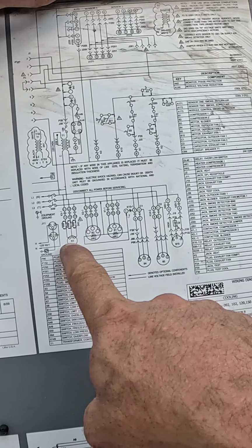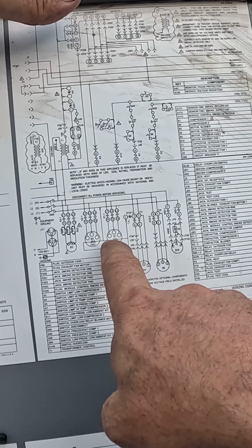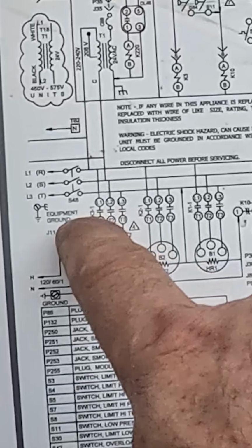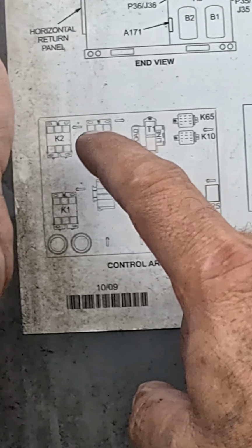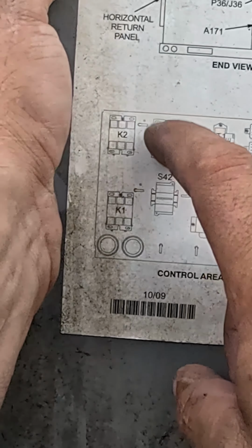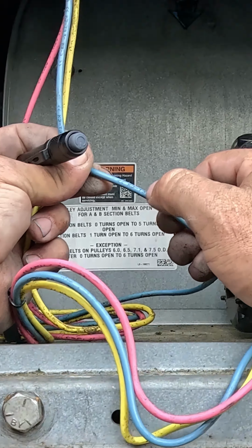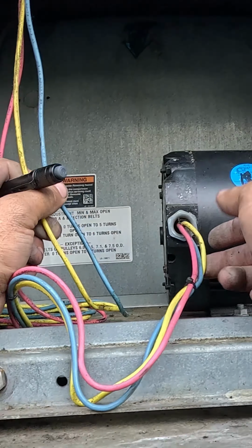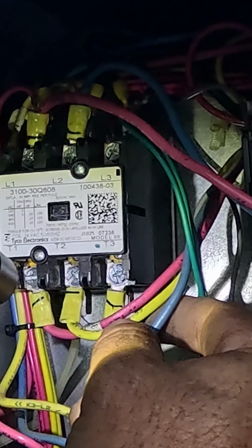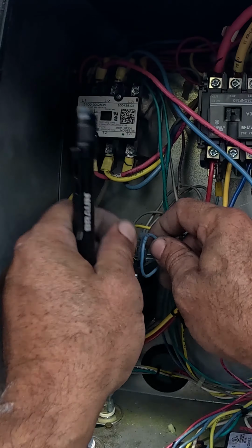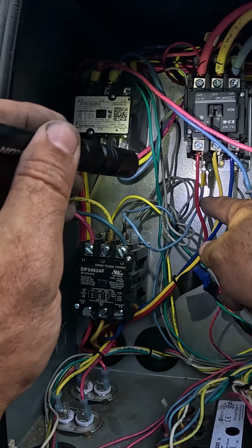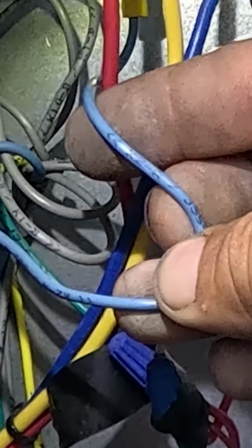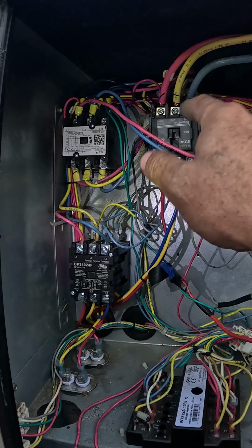because obviously B3 is not right next to the compressor. But we can follow this back to K3-1, which again is telling us it's this one, but in reality these two are swapped. Because when you look, the wiring is saying K3T3, K3T2 for the blower motor. This wire is labeled K3T2, but it's in the T2 location. If we look at this blue wire that's actually energizing K3, we'll see that blue wire is in fact labeled K2. That's interesting. From the factory, these two have gotten switched.